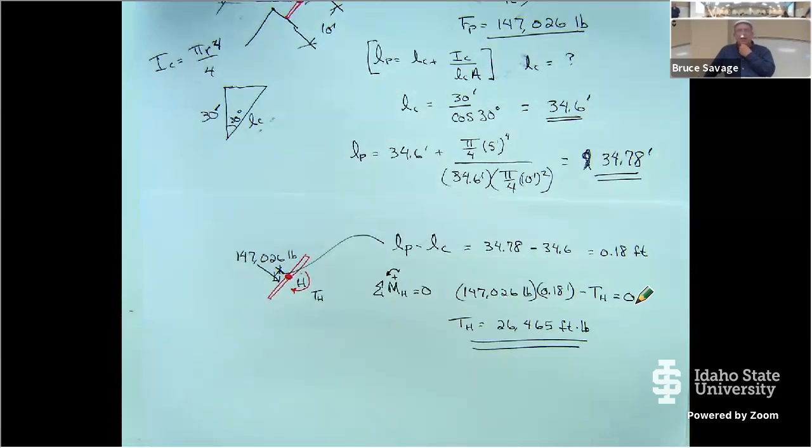But yeah, I'm glad to see that you're actually thinking about applying these principles, and could we fix this? Could we make it better? Because that's how better solutions come about, right? But understanding that there's a full range on all these things, you need to consider that it can also change the design, because we don't always just design for one parameter. We have to design for the parameter across the whole scenarios. And in this particular case, the change in direction, if we went vertically down and then shot out, cavitation would be a big concern, and that would not be allowed in that scenario.